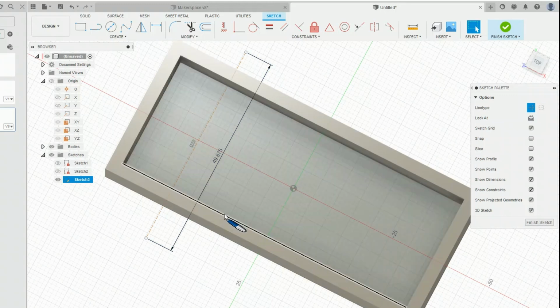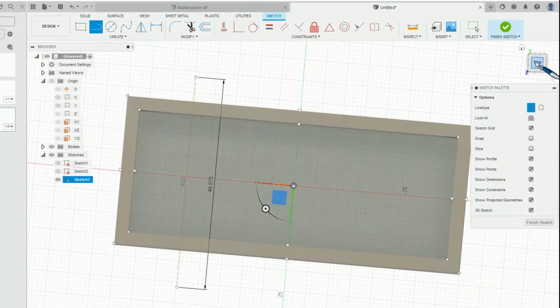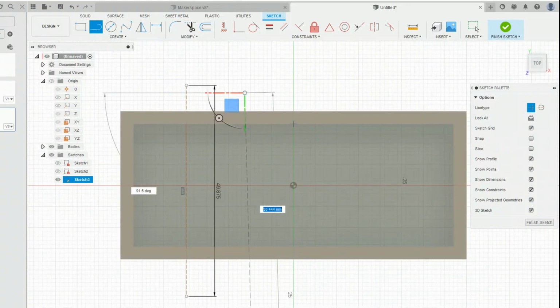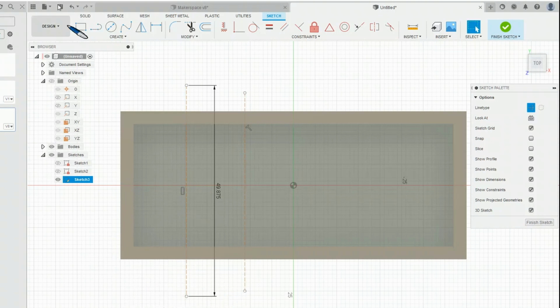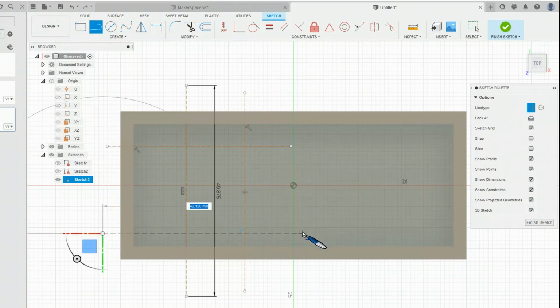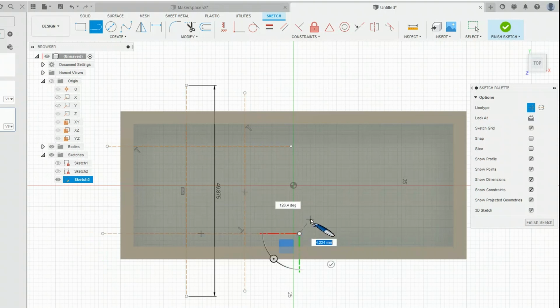It's locked in a length in this case for me, and we'll probably change that, or we may not need it at all. So I'm just going to draw a couple of lines the same like that, just to make life easier. I'll square it up, which will make my 90 degrees easier to draw. You'll see if I just hover, it will just snap to that 90 degree point. So I'll draw 2 that way, escape, whoops, wrong one, that one, and another 2 this way. If after I've clicked the second point of a line, it doesn't join another line, it will continue and try and draw more lines. So just hitting escape or return will end that at that point.